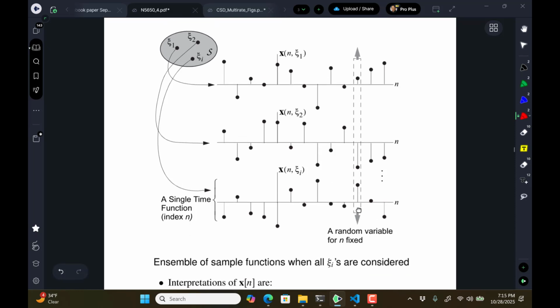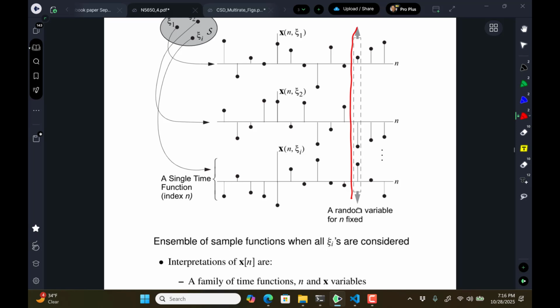And then we look at what happens down through one particular time instant, and we can say what is the mean and the variance at that time instant. And then if we shift it back and forth, it might change with time. And then we'll also be getting into statistics where we're going to sample at 2 different vertical sampling instances and then care about what is the correlation or covariance between those 2 vertical line points. And that is going to lead to the autocorrelation function, where we evaluate what happens as we lag at different time values. We'll have the so-called autocorrelation function.